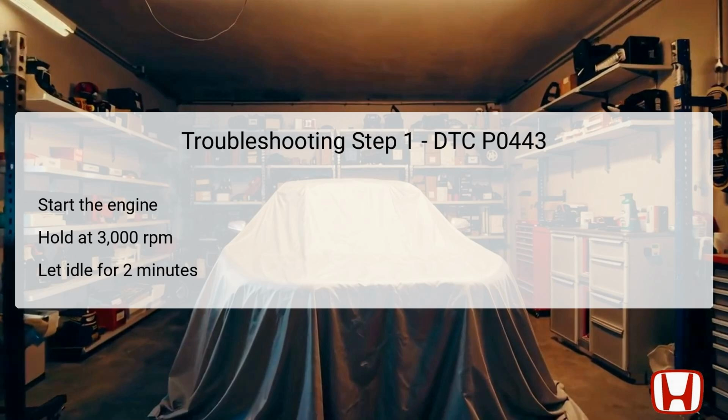Furthermore, this period helps to activate the radiator fan, which serves to regulate the engine's cooling system. After maintaining this state for a duration of 2 minutes, the vehicle should be allowed to idle, giving the PCM time to receive and process signals from the Evap canister purge valve. This procedure does not require any special tools, but is invaluable for assessing the current status of the system.